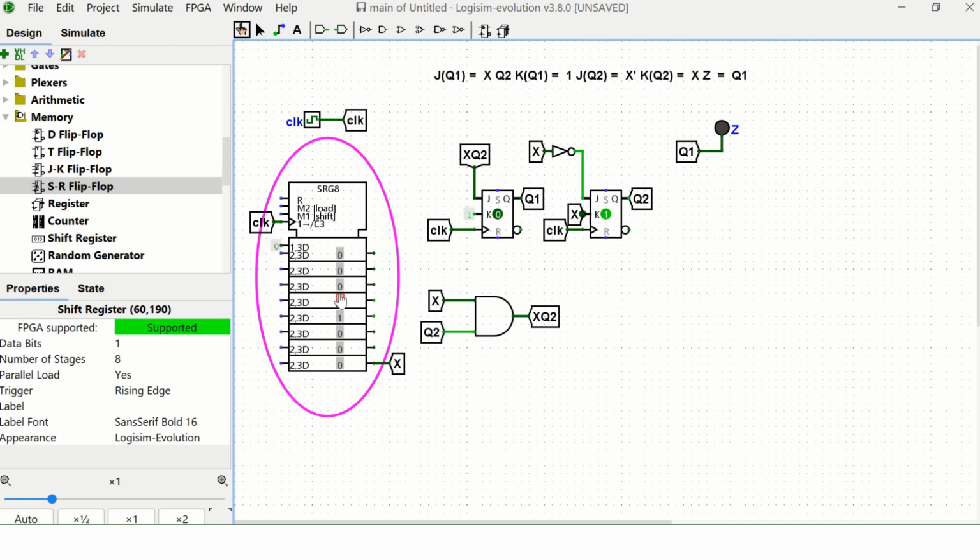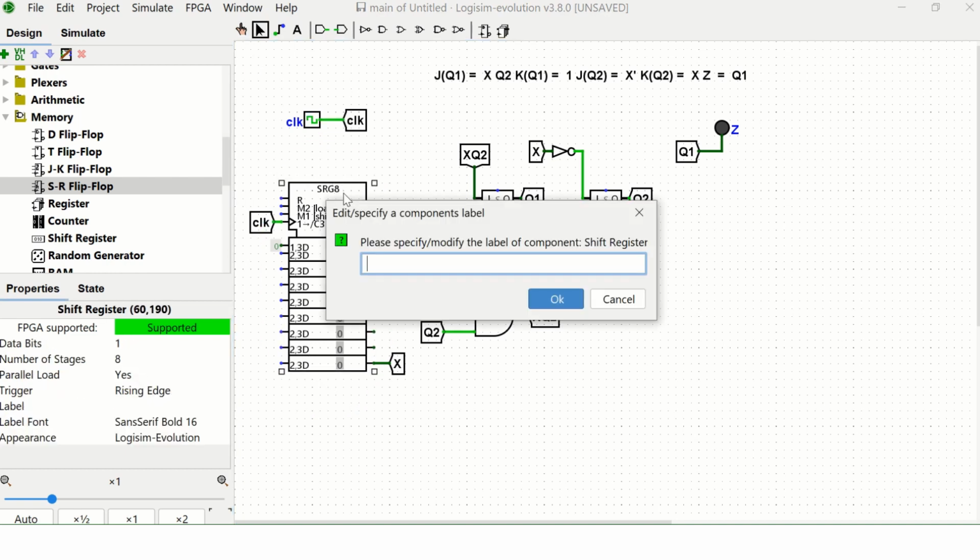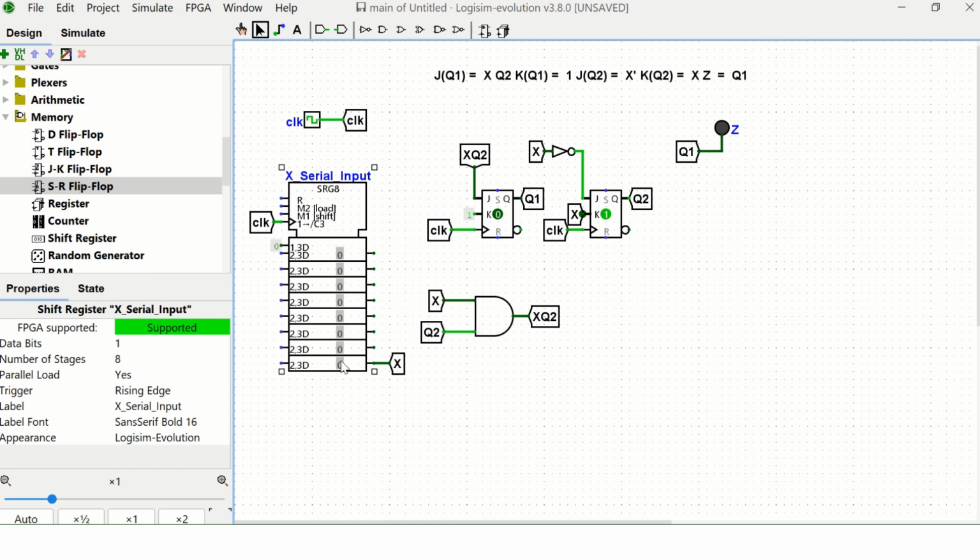I can have a lot of ones here, for example. Again, there is 0, 1 sequence. After the 1, it should be detecting it. Then the light should be off. So this is how the circuit, a simple sequence detector, works with the shift register as the serial input. So this is the serial input, our X. This is the one that goes either 0 or 1, which we have in the next state column. And this is the circuit with the flip-flops, and this is our Z output.